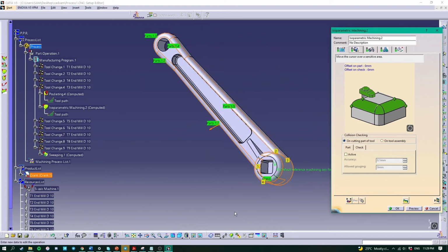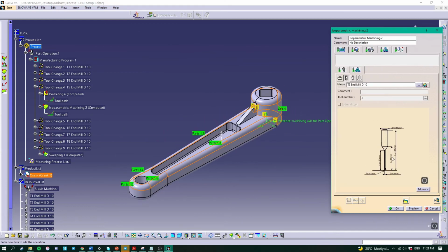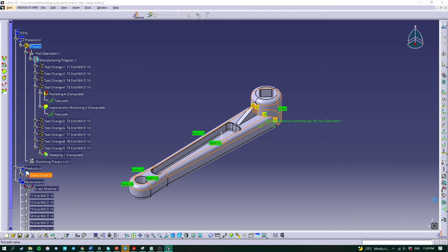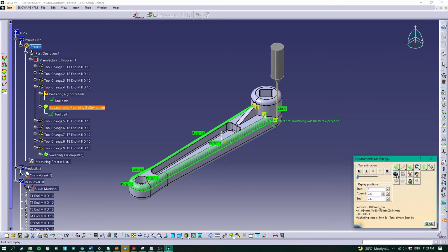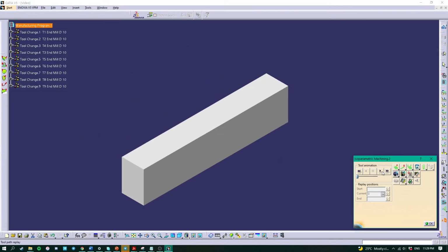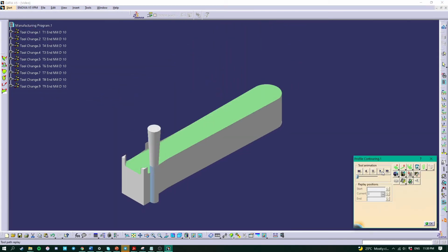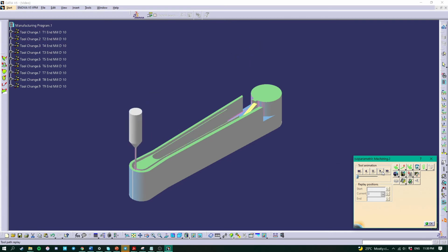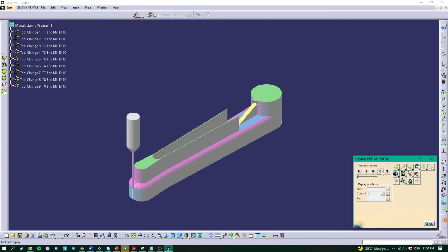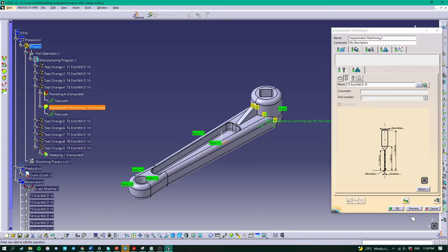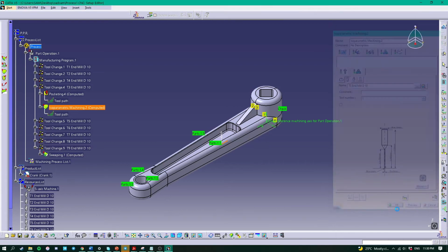After that, we set the tool. We use the end mill with the diameter 2 mm and set the axis of the tool movement. And as you can see here, this is the movement of the tool. The machine removes the material 0.2 mm, and then this is the result of removing the material to make the part fillet. Then click OK, move to the next machine.